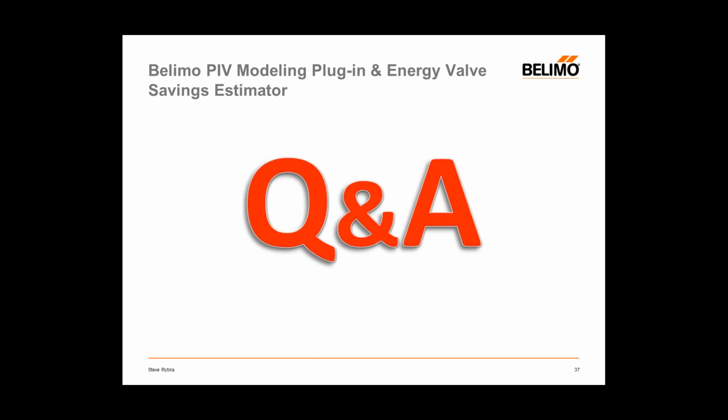In both eQuest and Trace 700, which pump curve is used for retrofit applications? So that's going to be the 5 to 30 PSI curve, not the 5 to 10.